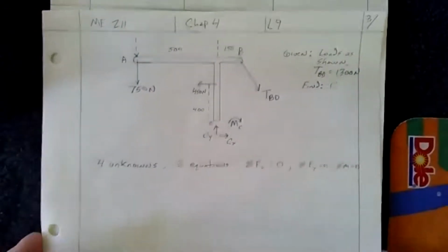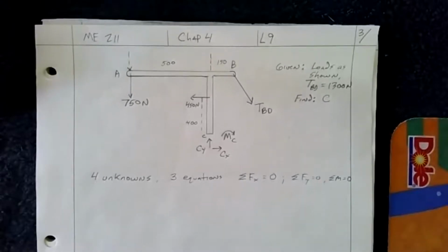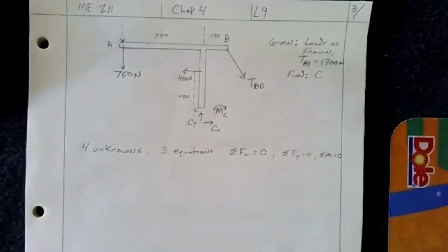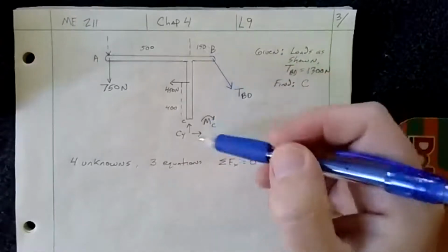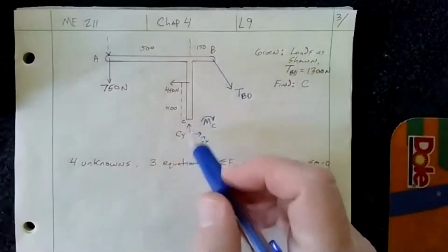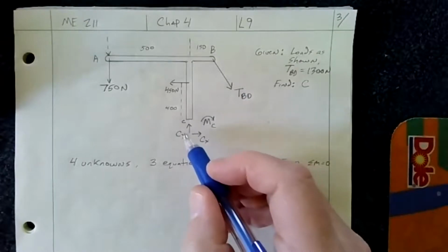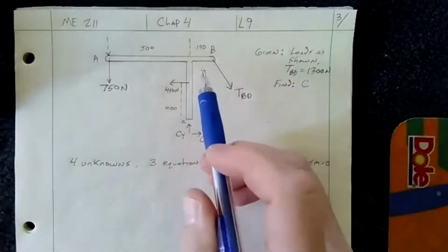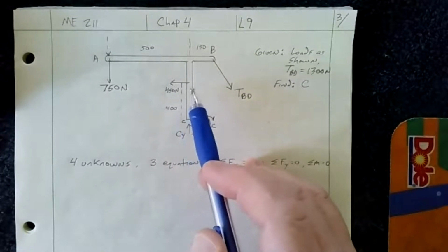So here's our drawing again. Now in this one, we look at our free body diagram. Hopefully you had a chance to draw it on your own beforehand, but we know that C, because it's mounted in the ground, has C sub Y, C sub X, and a moment at C. That means the forces up here don't necessarily have to balance like they did earlier.